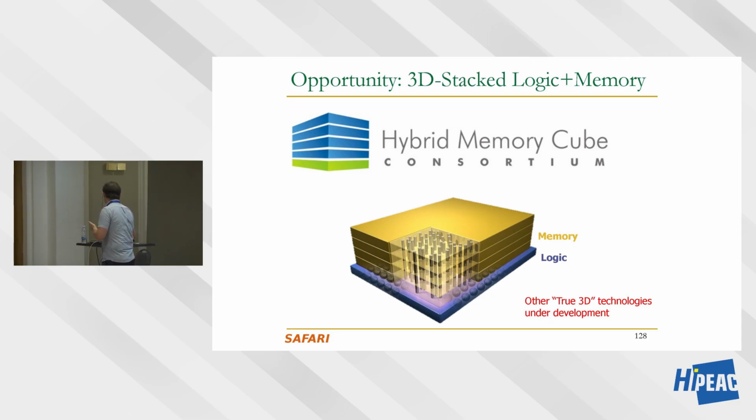Basically, because of 3D manufacturing technology, you have through silicon vias, which are not the best way of connecting through the stacks. There are better ways of doing it, using monolithic 3D fabrication, for example, but that's future. We're not even talking about that in this work. In the logic layer, you can put any kind of computation. That's our assumption. There will be some industry people who will tell you that you cannot do that. That's because their logic layer is not good today. They can make it better, and they're going to make it better. 5 years down the road, if they don't make it better in HBM4, come and tell me that I was wrong. I'm happy to be wrong. But I think they can make it better.